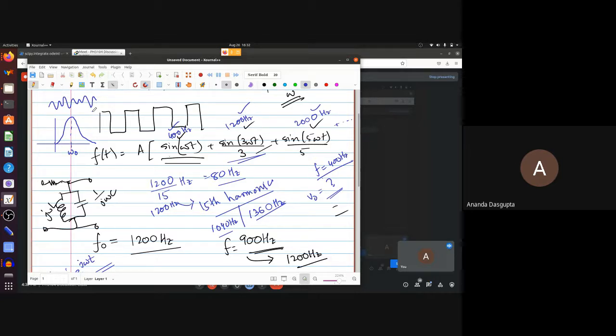So if your radio or your television actually amplified all of those, and you got to hear all of them together, then the whole thing would be a disaster. You would not be able to pick out anything. The tuner essentially picks out a range of frequencies close to the resonant frequency, and that is what you get to use it for. These are used for tuned amplifiers. These are used in conjunction with amplifiers basically to pick out certain frequency ranges.